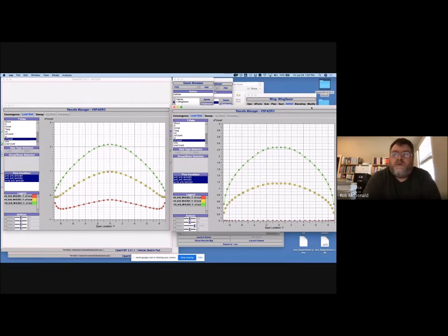The one on the right is the one without twist, and the reason I know that is it's an uncambered, untwisted wing, which means it's completely symmetrical, which means that when we run it at 0 degrees angle of attack, there's going to be 0 lift. It's a flat plate, so it's 0 lift. That's why the lift distribution, these red dots for the 0 degree angle of attack case, is perfectly flat. So I know that this perfectly flat one is our uncambered, untwisted case.